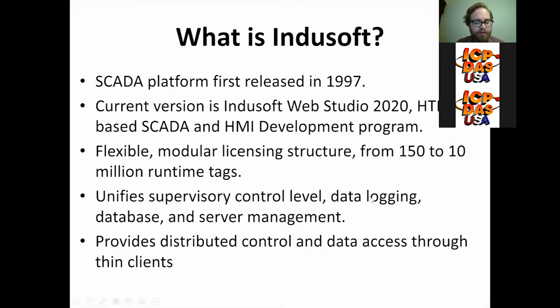Indusoft acts as a coordinator between different networks. It offers 250 native drivers for every major manufacturer of PLCs and controllers. Like any SCADA platform, Indusoft allows you to automate industrial processes at the supervisory level by integrating controllers and PLCs with your data acquisition system, allowing distributed controllers to respond to sensor feedback.